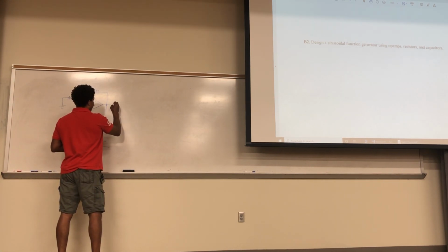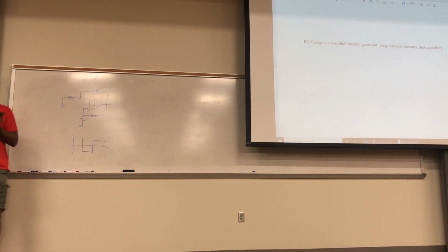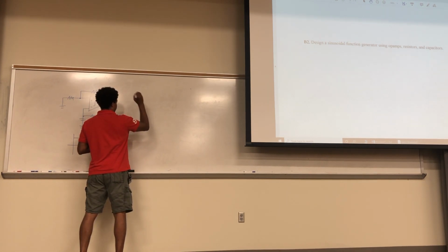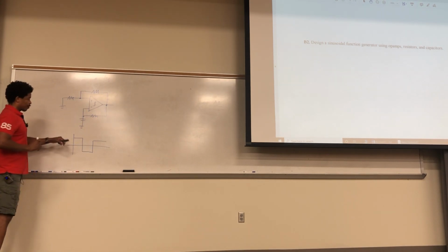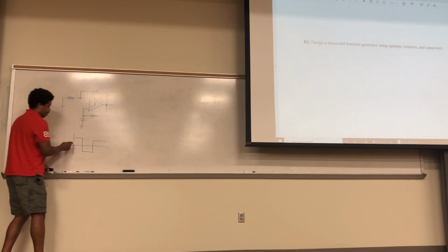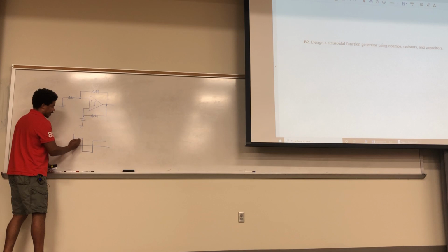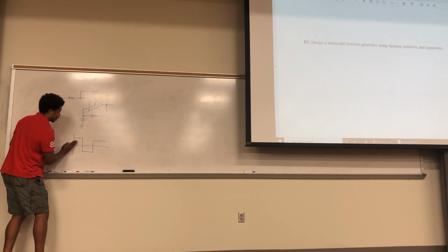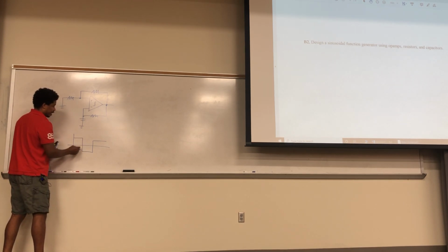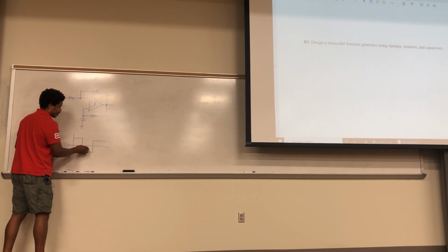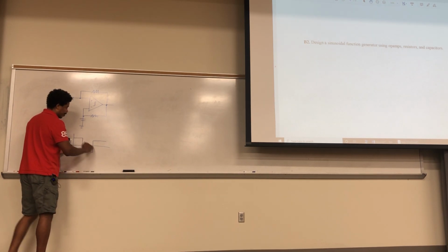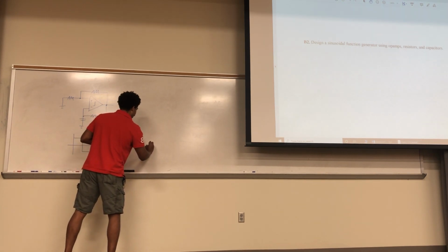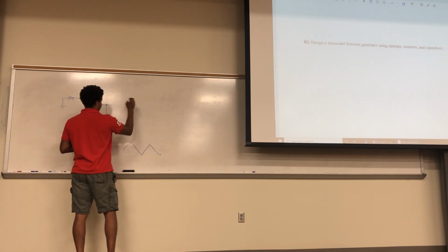After that, it goes into a what? Well, yeah, the integrator. Exactly. Because the integrator will take it to a triangle, right? If this is just a square wave and you're going to integrate this, as you go through time, you integrate these little rectangles, and that builds up linearly like a triangle. And then you subtract the rectangles, so that decreases it, but it's linear. So this next step just gives you this triangle wave, but you need an integrator for that.